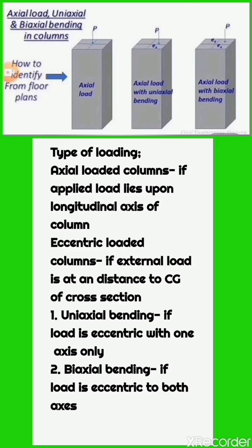Eccentric columns are further classified depending upon whether they bend or buckle about an axis. 1. Uniaxial bending: if the load is eccentric with one axis only. 2. Biaxial bending: if the load is eccentric to both axes.